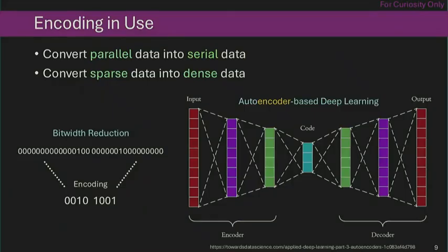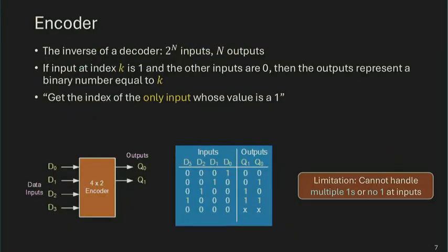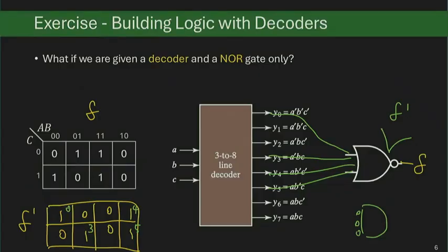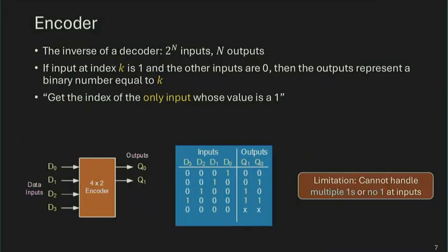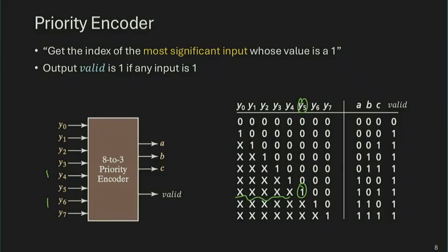So that's everything about the data path components. We have seen multiplexer, which is essentially a way to apply Shannon's decomposition theorem to implement functions. We have seen encoder and decoder. And you can usually use decoder to implement functions because that gives you all the minterms, and minterm expansion is always a way to implement a function. With encoder, you can hardly use this to implement a function. This is more used as an analysis component. You cannot generally use it to implement an arbitrary Boolean expression.